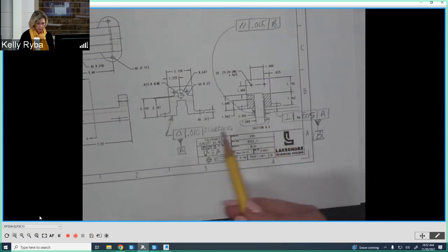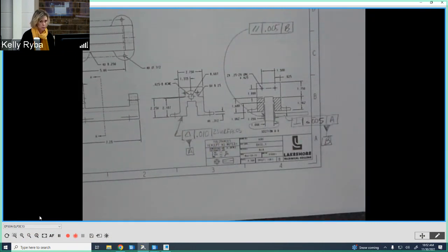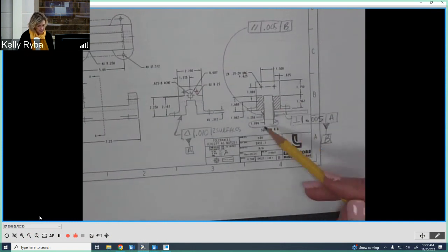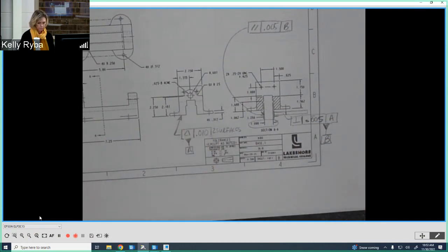If there's more room over here, you could do that over there as well, okay? You always want to try to keep your dimensioning in the same view, anything for GD&T and size. So best to try to get it in here, but if you can't, you can default over here as well. So that's going to be looking at that cutout. Those would be appropriate for the cutout.